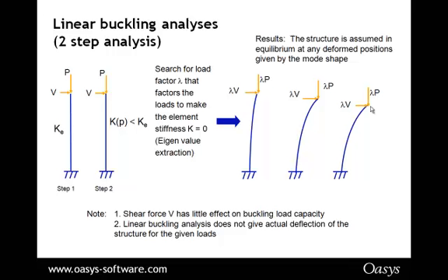In fact, GSA will normalize, that is, adjust the deflected shape until the maximum deflection is 1 meter. Note also that in reality this could be 1 meter in either direction. So you can get the axial loads, but you can't get the deflection values, and you can't get the moments, because obviously the moments are based on that large deflection, which is not real.